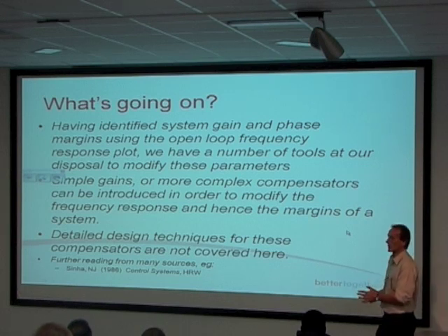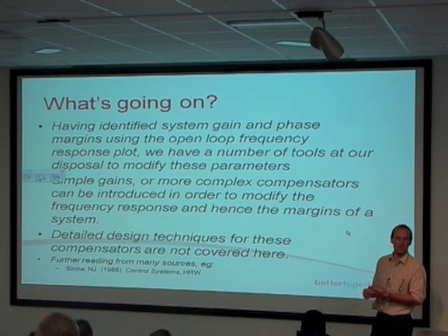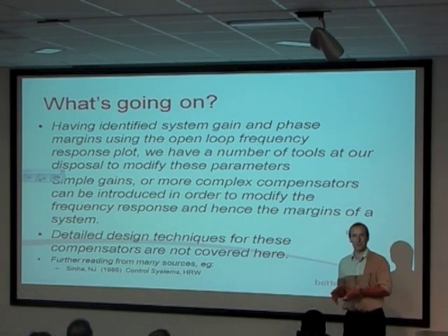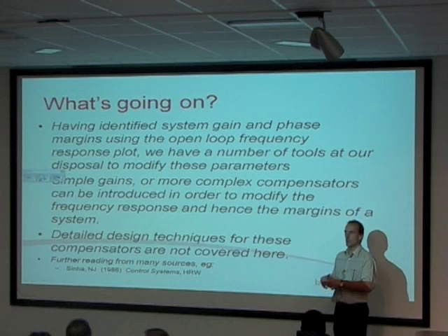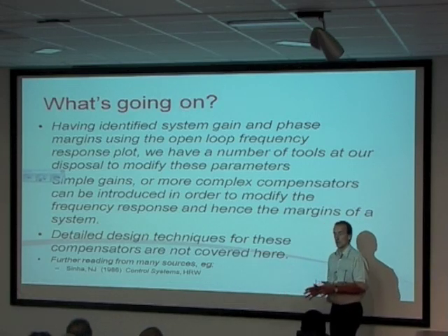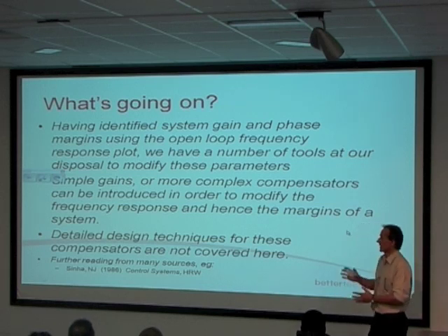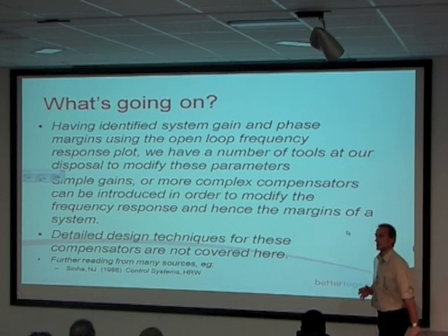So we introduced these more complex compensator patterns. Lead compensators, lag compensators, and then ones that are a combination of the two, lag-lead and lead-lag. What we can do with those is some more specialist modification of that frequency response plot, typically by looking at what's happening in a phase plot and moving things up or down to suit ourselves. In this module, unfortunately, we don't have time to cover the detailed design techniques for these, but you will find it in any decent control text.